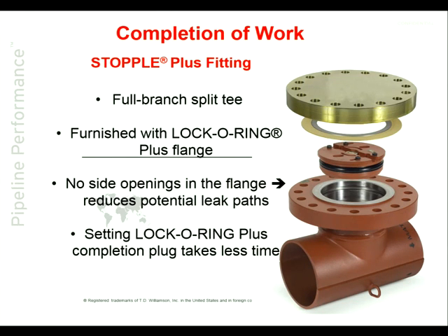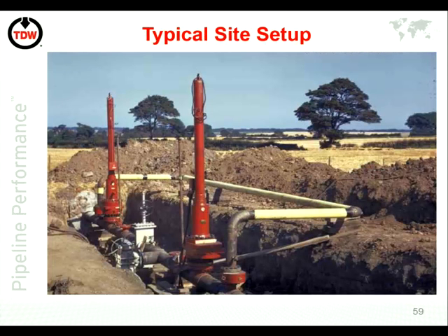But basically, these are large hot tap fittings. You can actually put a small fitting on here, which is not full circumferential. The same mechanism, and then it's exactly the same setup. You would drill a small hole, fit a small valve, and then you would release when you wanted to. Is this little fitting welded? It is, but it might not necessarily be full circumferential. It might just be a fitting on top of the pipeline.